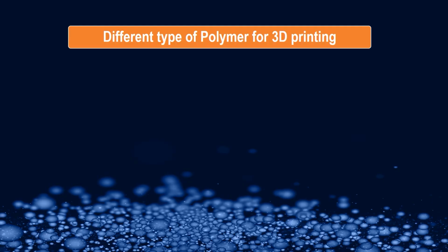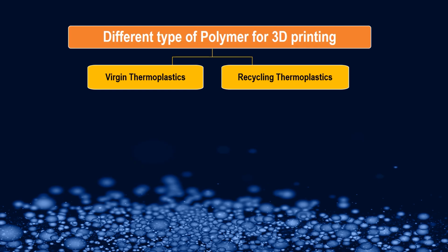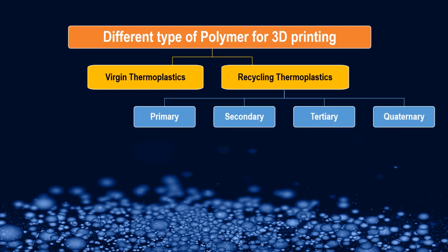As regards the different types of polymers, we can use virgin as well as recycled PLA, ABS, PCL, PVDF, PETG, TPU, nylon, PP, PEEK, etc. There is a long range of polymers that can be processed over here. Like I have already explained in my previous talk, between 100 to 300 degrees Celsius melting, n number of polymers are available, right? So I have to be very sure for what particular application I am going to use it, and accordingly I can select this, maybe virgin, maybe recycled.